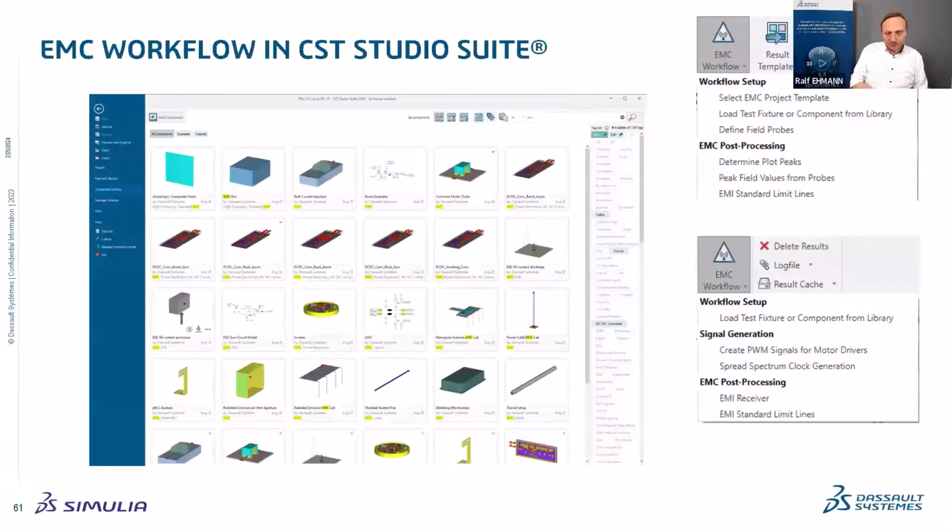You have seen the models that I have used today during the presentation, and you will find almost all the models, the radiated emission not yet, but all the other models like this inverter, this line, some monopole emission, right after you have installed CST or the BCI clamp, because in CST you will find a so-called component library where most of these EMC related models are present. So you can click there, start the model, it's set up completely, it's ready to run. You can check how the model has been set up.